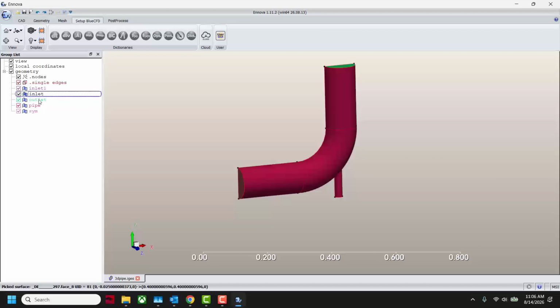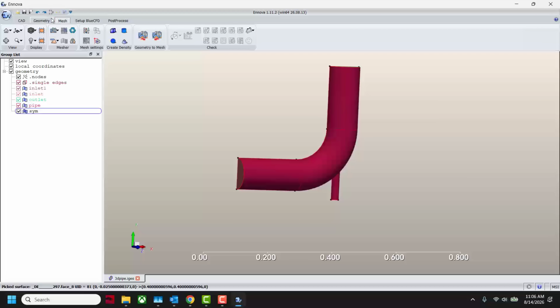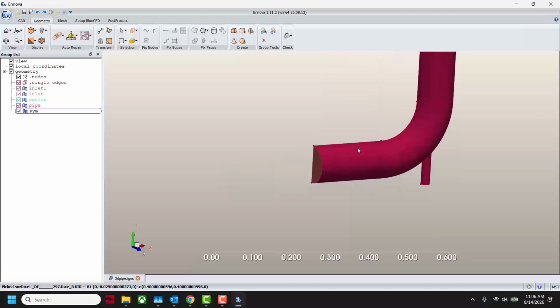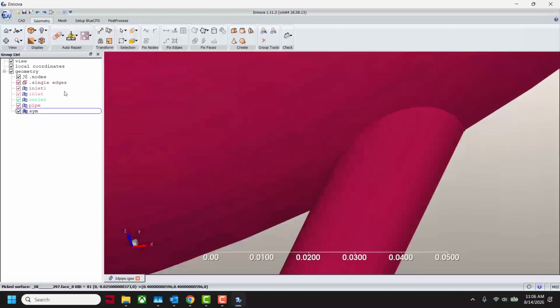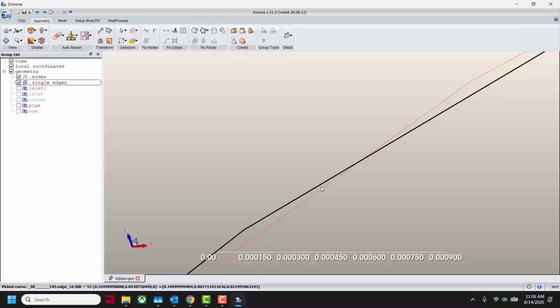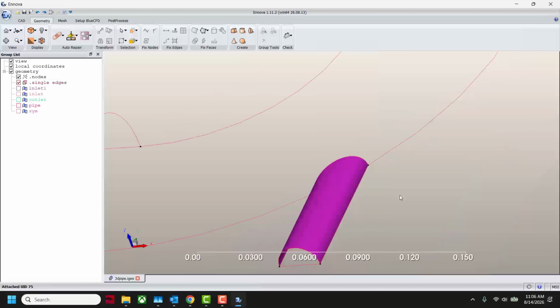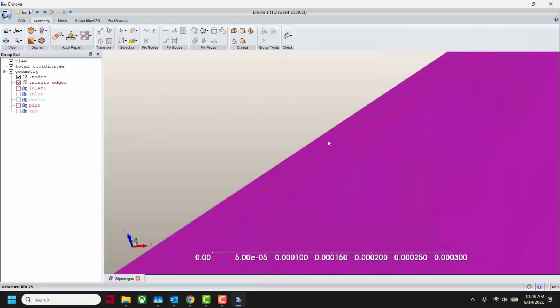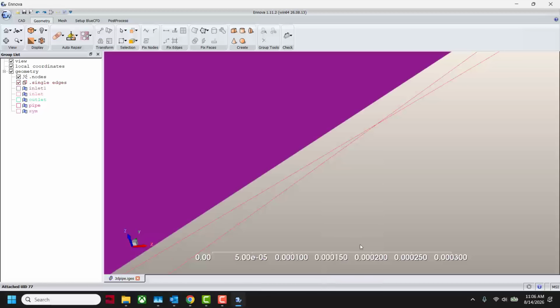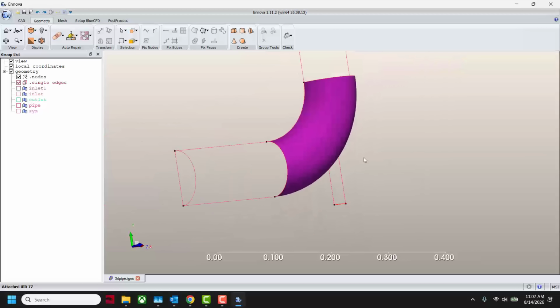You can see them here, inlet, outlet, but we don't have a computational volume. In order to get to a computational volume in this case, we need to build the volume and repair the CAD. If you have a look at these various surfaces, if I hide the surfaces, you can see it better. Typical IGES, the different surfaces are close, but there are two surfaces there. If I pick this surface and look at the face, it's that one there. And if I pick this surface, it's that one there. So they're all kind of in the right place, but they're not stitched together.